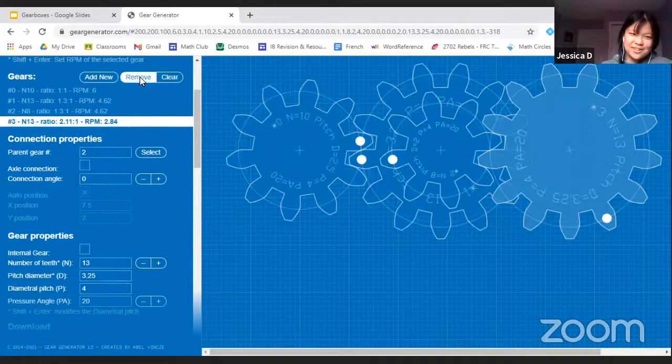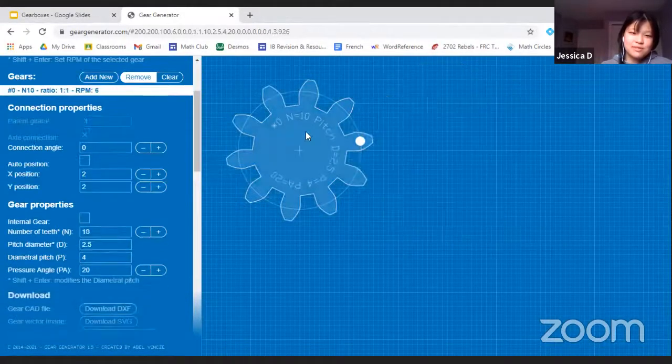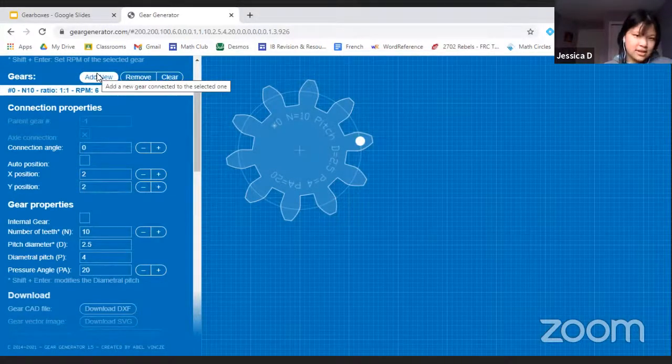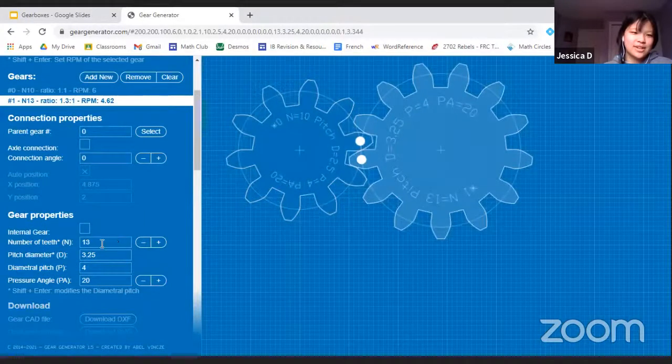The first way that you could go about this, which I would prefer you didn't, but if you really want to, you can do just one stage. What does that mean? Well, we're going to have to start with a gear. So this one has 10 teeth. And to get a gear reduction of 100, what are we going to need to do? We're going to need to create a gear with 100 times as many teeth, so that this first gear will have to turn 100 times for every rotation of that second gear. So let's do that, I guess.